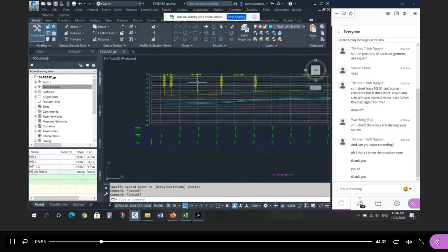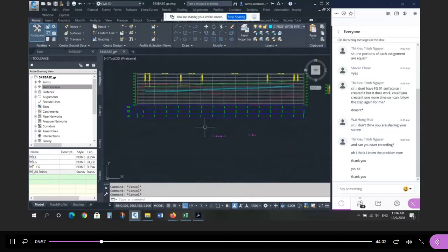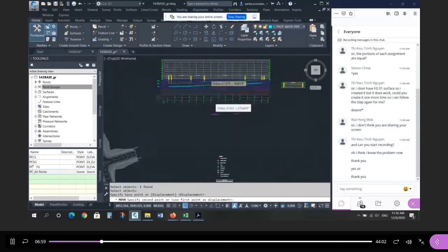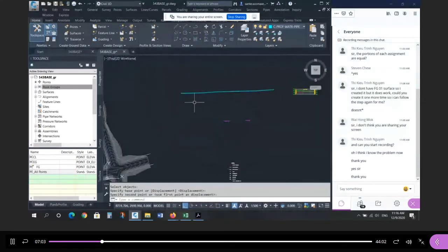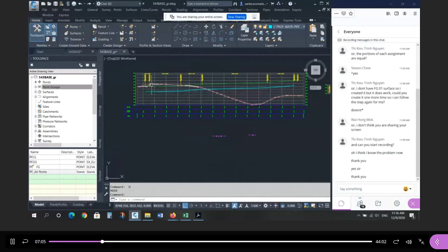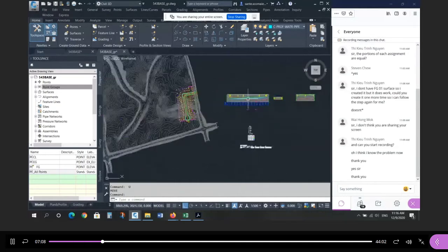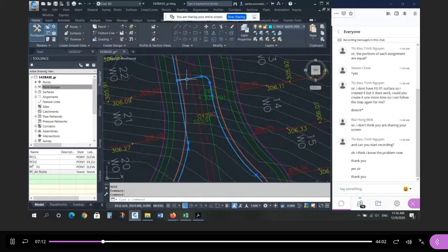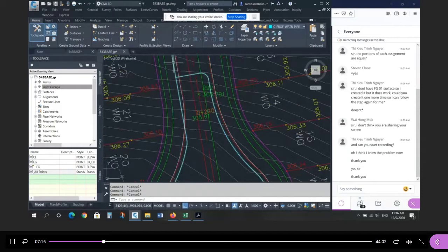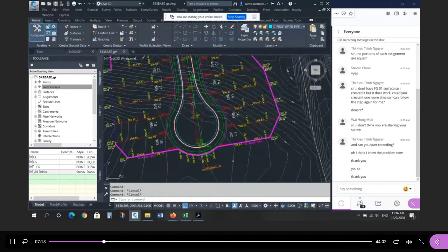Okay. Now remember, this is AutoCAD, right? If I move this, everything related to Civil 3D moves, but not the AutoCAD stuff you're drawing. Okay, so just keep that in mind. So now that I have all this, you have to remember the design of the water main, remember this return. Somewhere in here, there's a PVC pipe of 150, but the loop is a copper pipe. So let's take a look at that standard again.